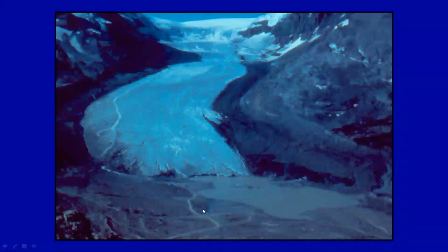All right, this slide is very important because we are seeing subsequent deposition at multiple points during this retreat. Over on the left-hand side, you will notice that a stream is coming out beneath the ice. This is carrying very coarse sediments that ultimately, when covered as the glacier retreats further up the valley, may in fact represent a favorable zone to develop a public or high-yielding well supply.